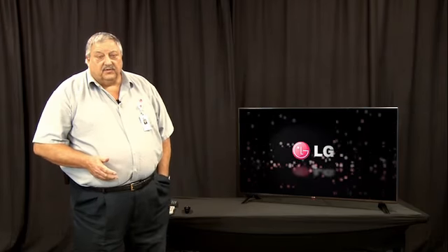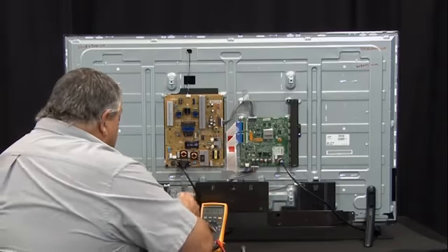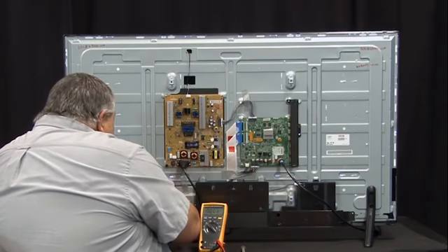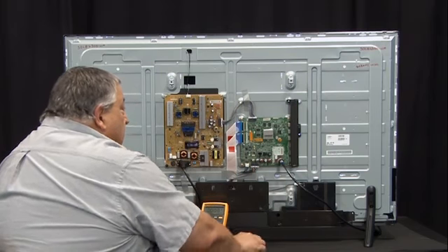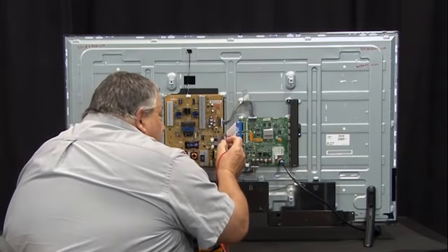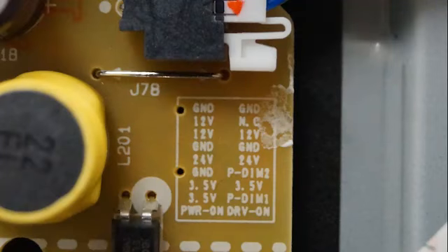Let's assume that we have found that all our settings are okay, but we still have no audio. The next thing we want to do is investigate those three major components. We're going to take our meter and attach it to ground and place it in the DC mode. Use the label indicated right on the power supply and look for your audio B+. Usually that will be between 17 and 24 volts.